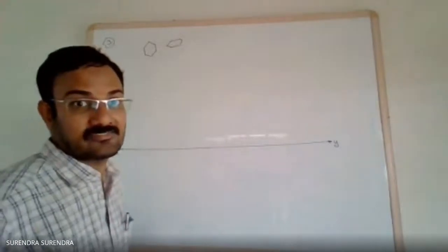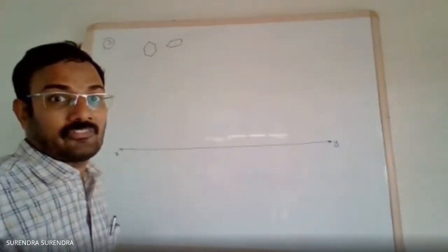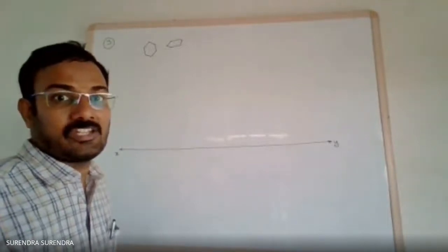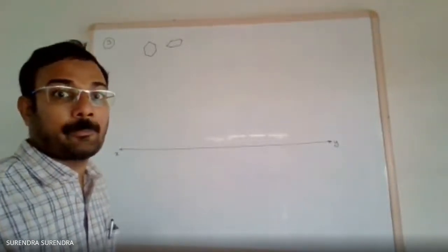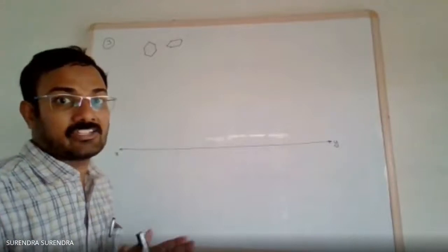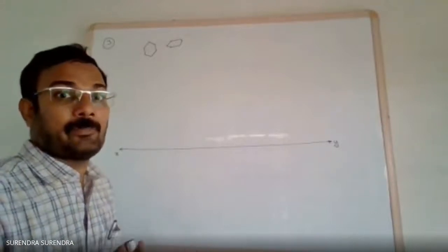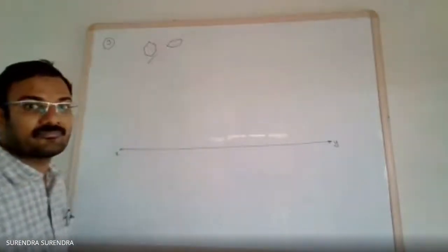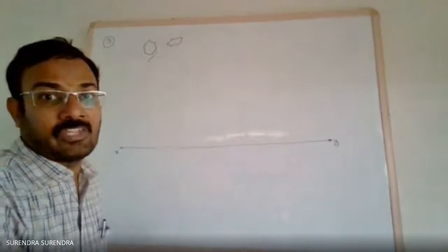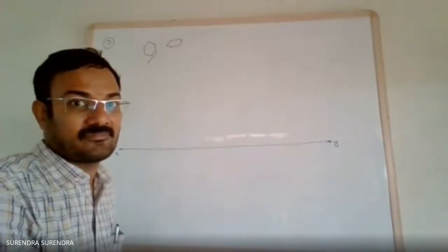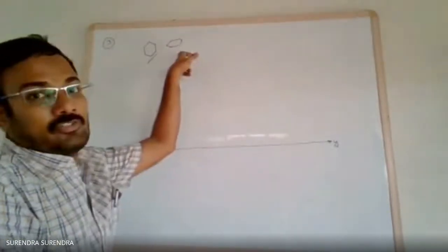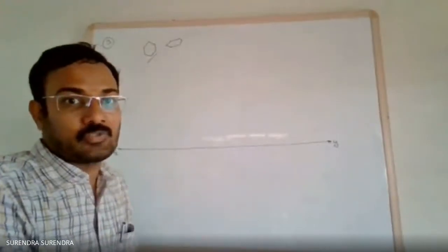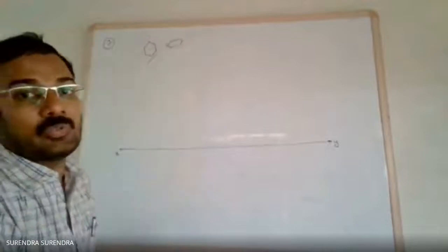Both are hexagons. So, when the problem is an edge-based problem, one of the edges on the reference plane or parallel to the reference plane. As we have to draw the edge perpendicular to XY line, we will prefer this orientation. Otherwise, if it is corner based, we will draw the hexagon as in the second orientation with two of its sides parallel to XY line.